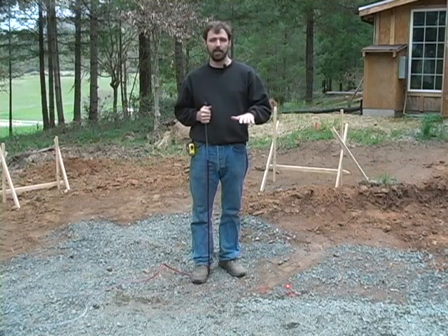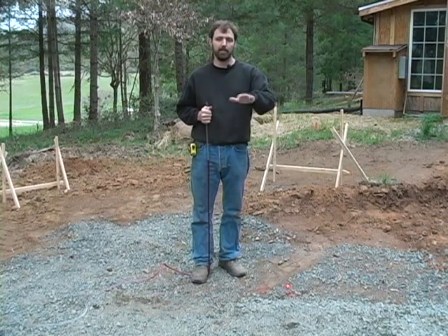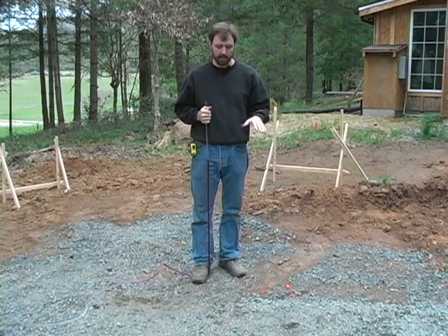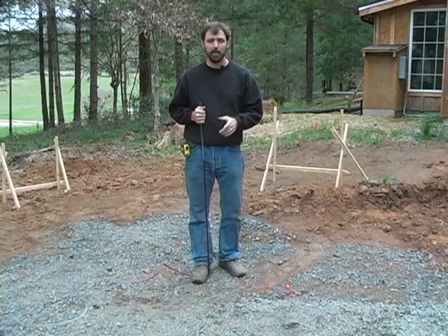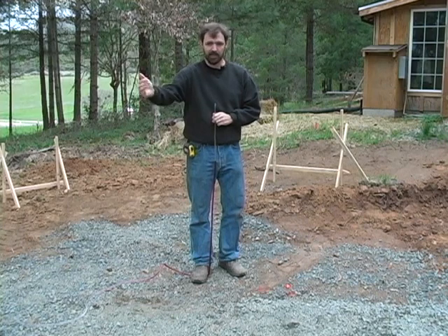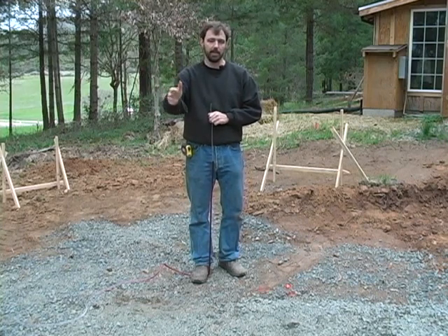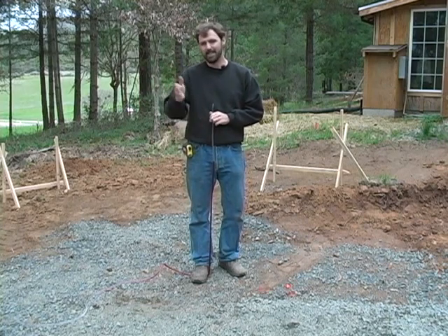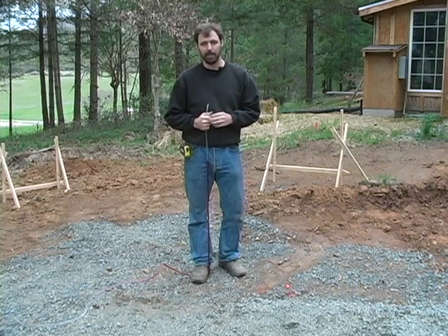This is going to give us an exact definition of where we're going to place our form boards. Now, we've established rough grade here, but we're still going to be off a little bit from perfect level from side to side. So what we want to do is find the high point. With the high point, we can then level out from there with our form boards, and we'll be able to fill around the outside of the form boards to hold the wet concrete in place as we pour. That's easier than digging the footings down even further into the ground.